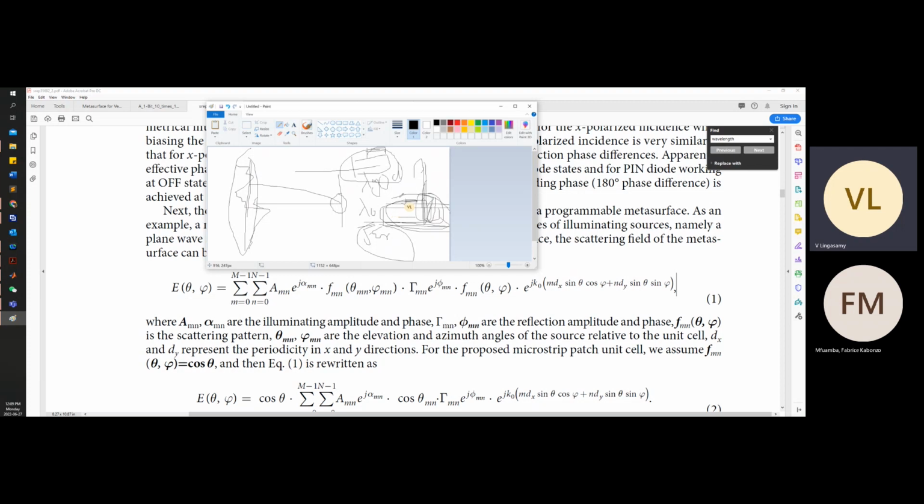So what you have to do is control this phase by making new, complex printing structures, new shapes. You can control the phase shift that is introduced by the unit cell, and thereby you can control the radiation pattern. Why? Because of this equation. You can see here, when you control the phase, I can control the overall array pattern as well.